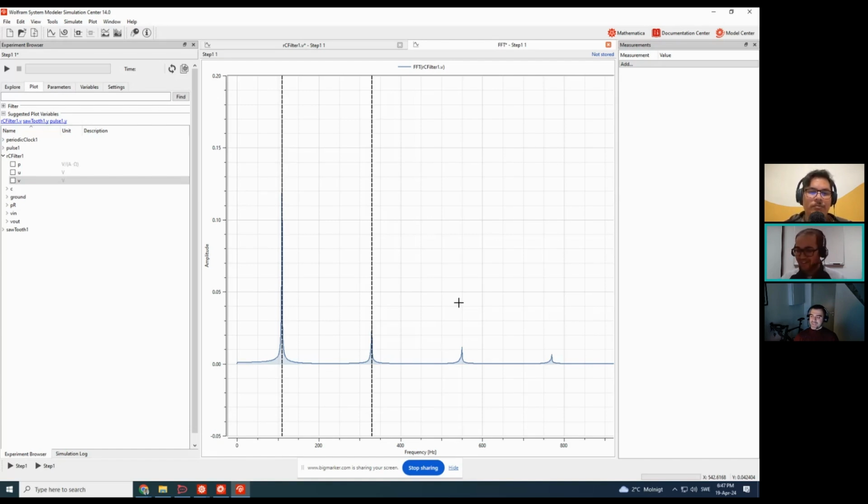Yeah, you answered really well actually. By looking at it, we can figure out whether we see the expected behavior. If we see unknown harmonics over there, unknown frequency characteristics, then in rotating machinery we can say, oh, there might be something faulty.